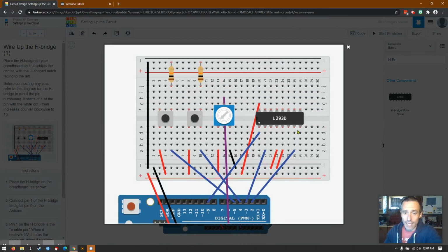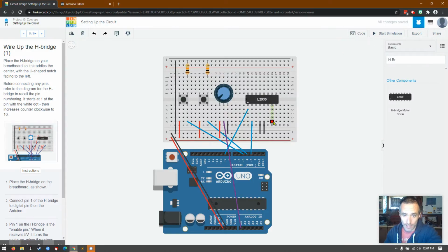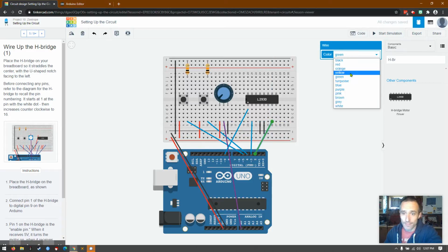And then they have this pin. So I think that was 5, 6, 7, maybe the second from the end. If I mouse over it, we'll see, but it's running to number 2. So the second from the end runs to number 2. Now it was blue as well. And so I will choose blue. And if I mouse over it, it says that's an input. So this will probably be an output to send signal to it to give an input.